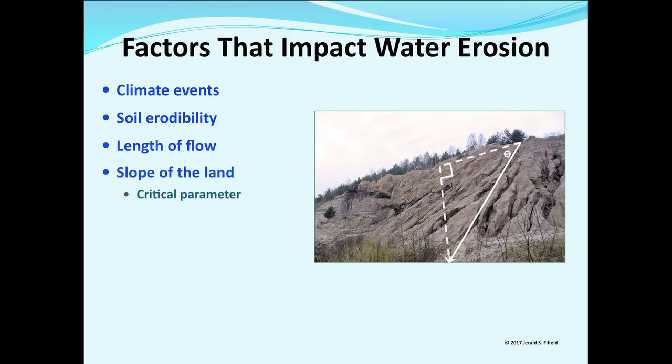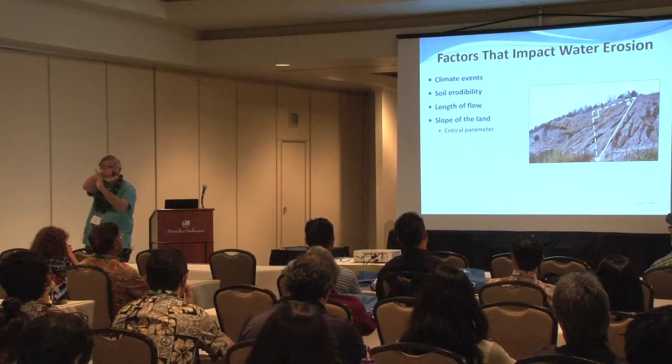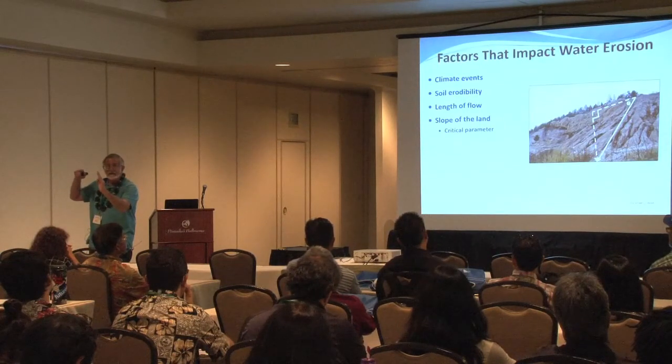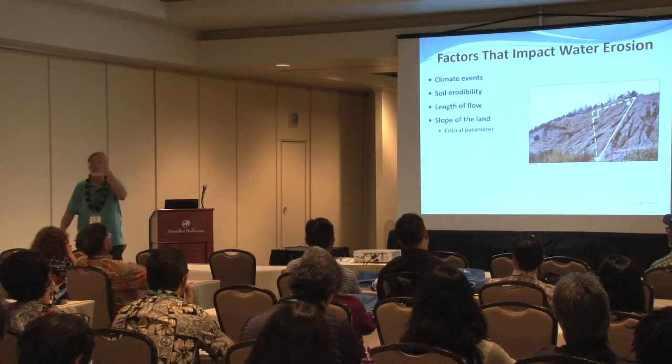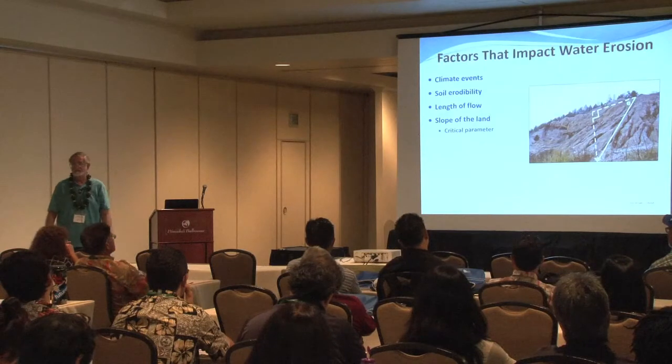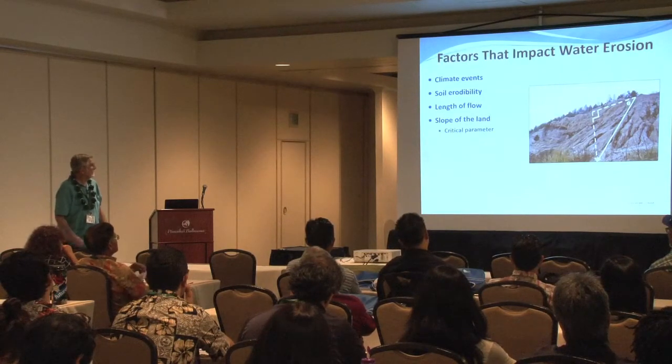Steep slopes are disastrous for you. Flat slopes, we love them in Colorado. We've got them. We also have steep slopes. If you've got steep slopes and you're putting up a little fiber roll up here, you just lost the battle big time. There's no way in heck you're going to be able to do anything except watch the sediment go into the Pacific Ocean. So you've got to be careful on these things.